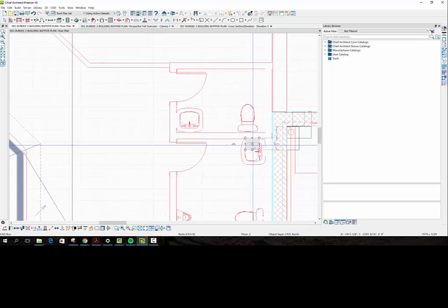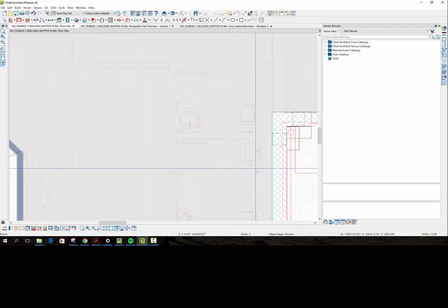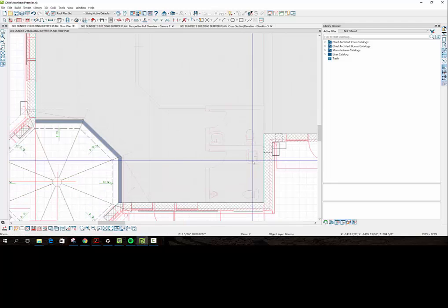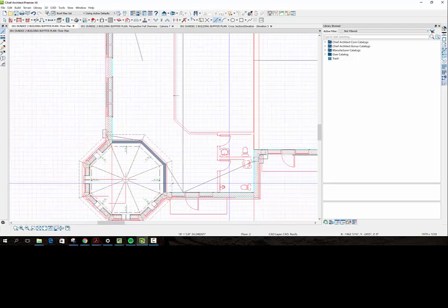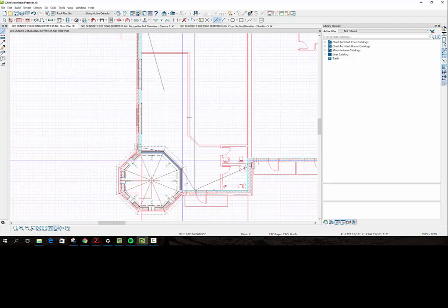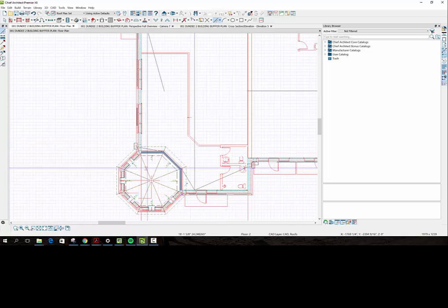There's our hole. There's our hole indication, and it should be somewhere like that's good. Right there. And now we got a hole there, we got a hole there. Now we're going to drain the water this way. And we find this line there, snap to it there. There's our cricket high point. This water's going around the corner of that scupper.